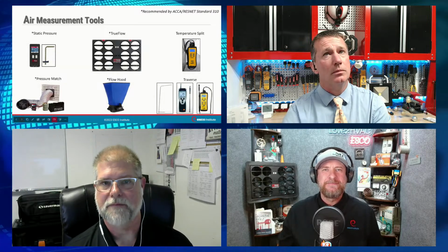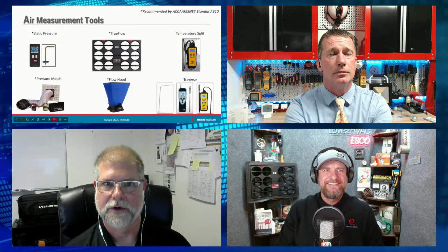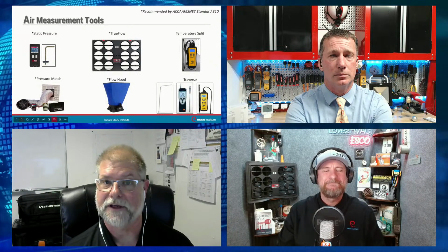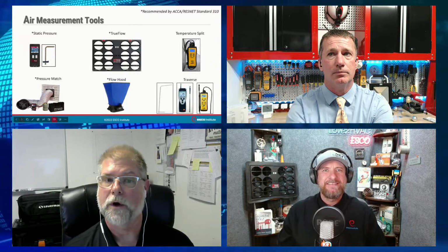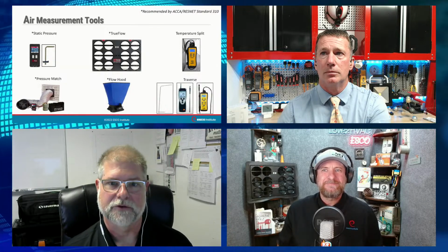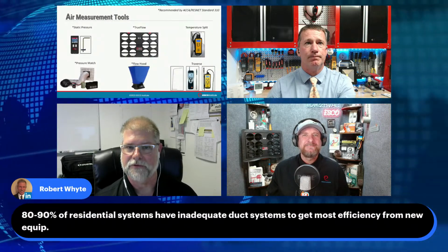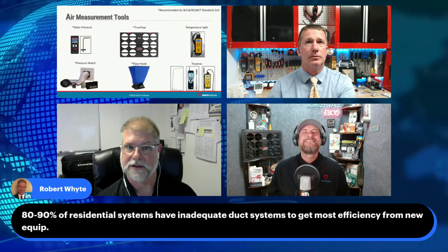temperature or enthalpy change. And we see measurements taken in different locations, taken out of context. Something that Ty pointed out, probably about a year ago, was that many professionals were using static pressure as a silver bullet, and they were taking it out of context, and they were trying to make it mean more than what it really did. And so I think one of the things we have to keep in mind is every measurement that we take should have a purpose, and we need to be looking for an intended outcome from that to help us troubleshoot a system and then understand how to explain it in terms that an average homeowner can understand.